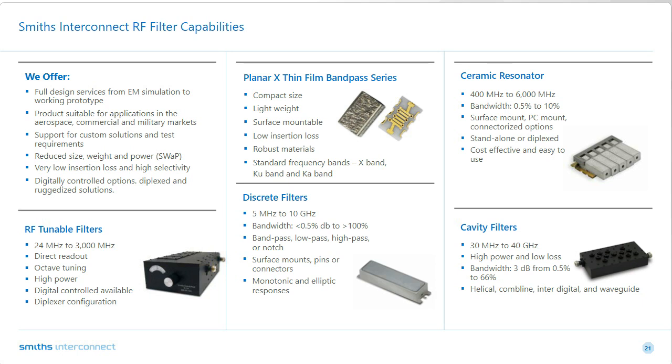Next one here. What about filter reentrance at 3 times the center frequency? Sure, I can take this one as well. Most of these actually probably will have a reentrance before 3 times the center frequency, but we can cascade low-pass filters to cover up anything that happens to pop up at those frequencies.